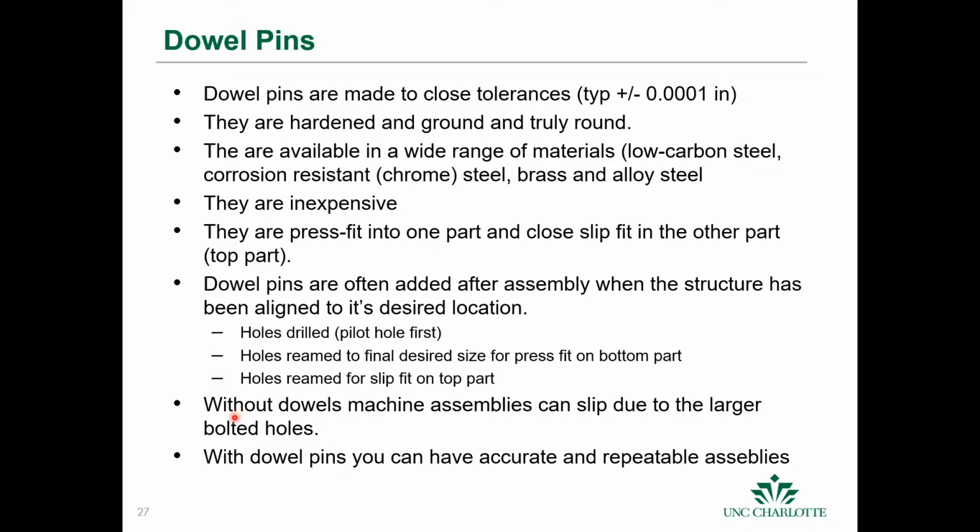Okay. So without dowel pins or welds, machine assemblies can slip due to those larger bolted holes. With dowel pins you can have accurate and repeatable assemblies.